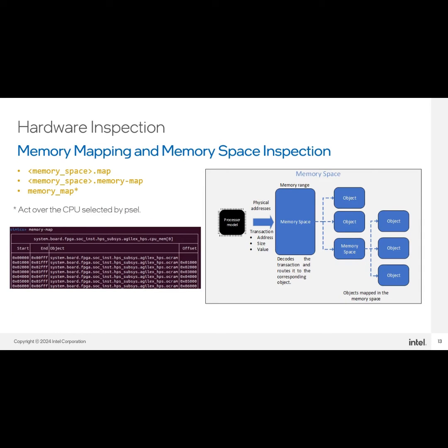A memory space is a fundamental abstraction in the Intel Simics Simulator, providing support for generic 64-bit address spaces into which memory and devices can be mapped. More concretely, a memory space takes a stream of transactions to an address space and distributes them to devices mapped into the address space in a highly efficient manner, while optionally providing address translations, byte swapping, and breakpoint support. Memory space objects can be cascaded to form arbitrarily complex mappings and support dynamic reconfiguration and remapping at runtime through attributes to support the modeling of buses with dynamic addressing.